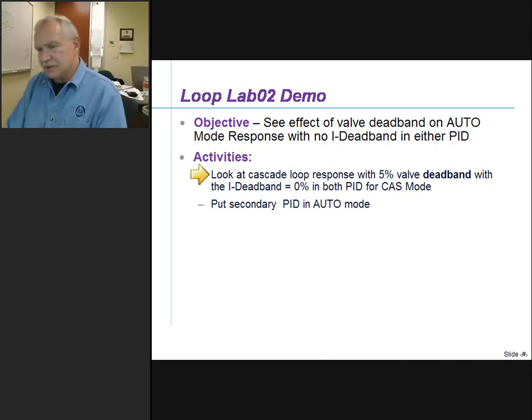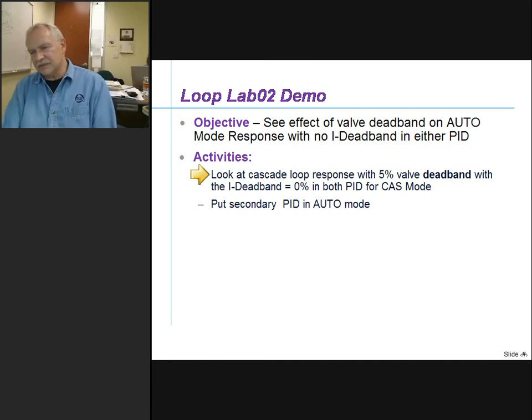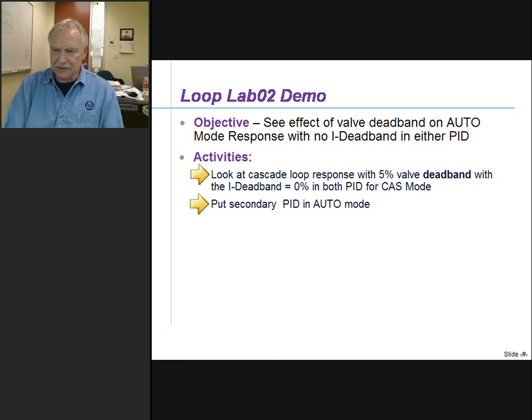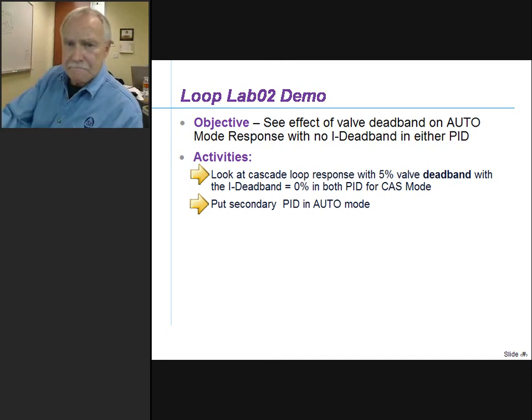So we can see here that we do have now an oscillation from the deadband. And one of the reasons why I chose to show this demo is because there is some misinformation out there, some rules that said, well, if you have valve deadband, you're not going to have a limit cycle in a self-regulating process.